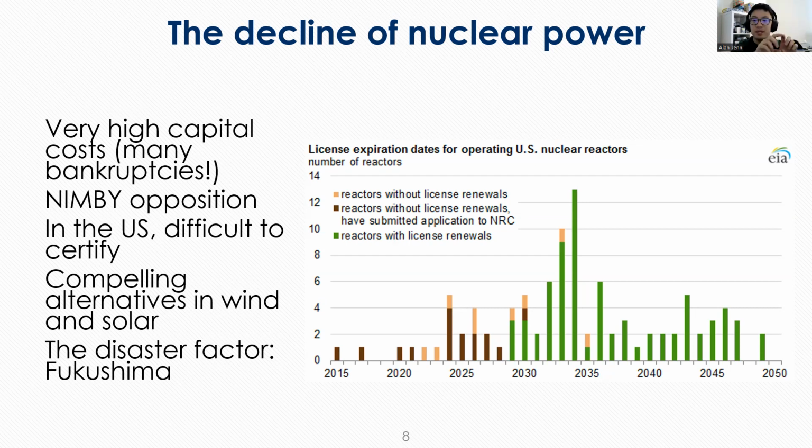You divide that by the energy produced, and that gives you a levelized cost, which tells you how much it costs to produce electricity, including distributing the cost of the capital over the lifetime of that resource. Then you can compare apples to apples, like the bang for your buck.